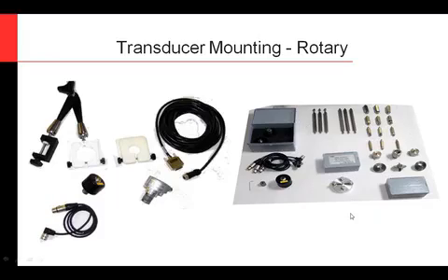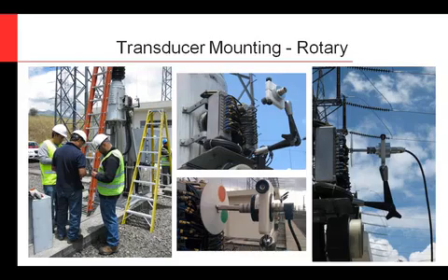And you'll see there's a variety of different brackets and bolts to hook onto different styles of circuit breakers. But here's an example. Generally what I've seen, most live tank circuit breakers use a rotary type transducer. There are occasionally, like anything, ones where you use a linear type, but most people prefer a rotary type on a live tank. So they came up here, and this is your open-close indicator, but we can hook directly to there, and it rotates along with that circuit breaker so many degrees, and however many degrees equates to a certain amount of millimeters in travel length.